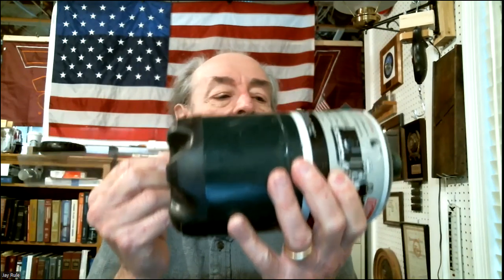And then the length of the tank. Clearly this is not a pure mathematical cylinder, is it? So I've got to sort of eyeball where the start and end of my tank are. I've got to make some engineering judgments. Very typical. You're going to be expected to do this, not necessarily in this class. You're going to be given input data, but clearly when you get out in a job, you've got to make these decisions on your own. Nobody's figuring this out for you. And so my estimate for the inside length of the tank is 15 centimeters. You could write that down too.